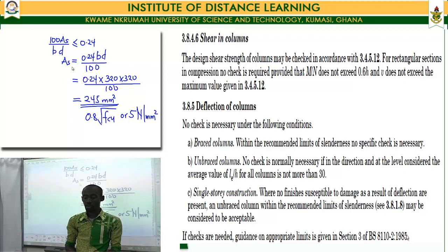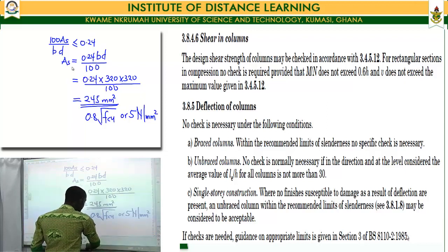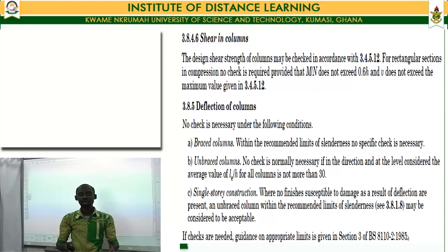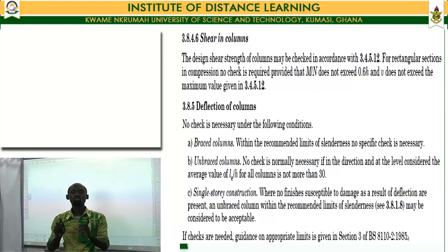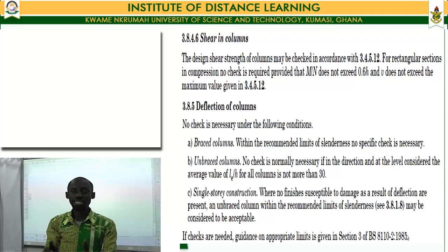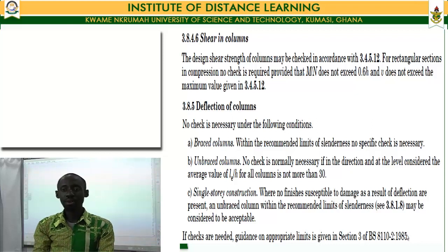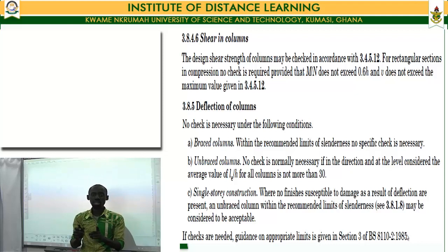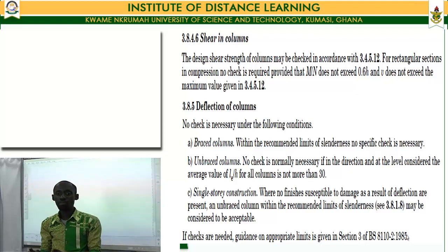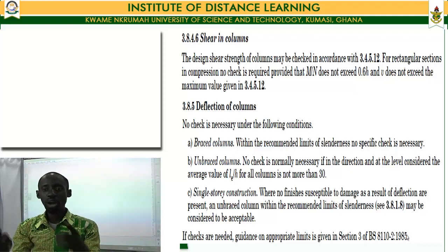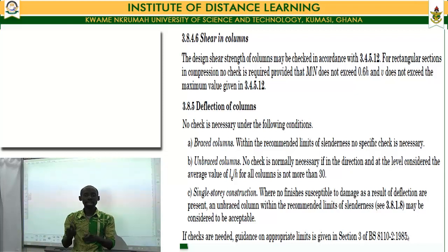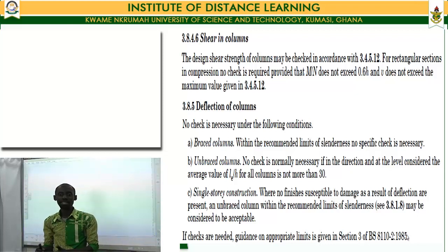Now, if we go back and look at our effective height, and our initial dimension, we constantly made sure that our effective length over the height of the column was not more than 10 in both the first floor level and the ground floor level, under which case our le over h is nowhere near the 30 limit being given.